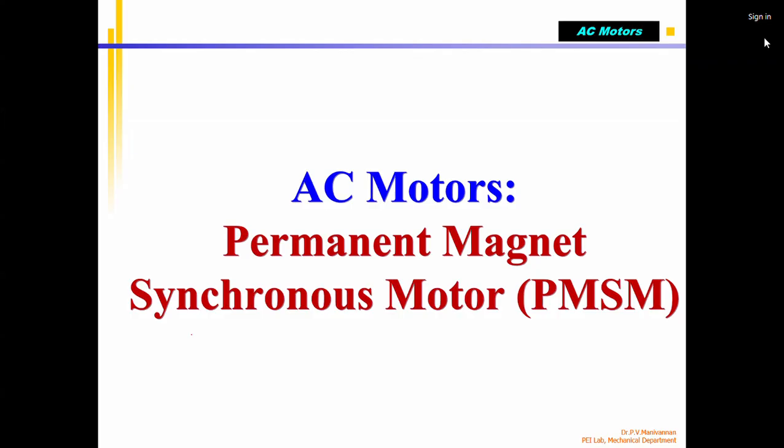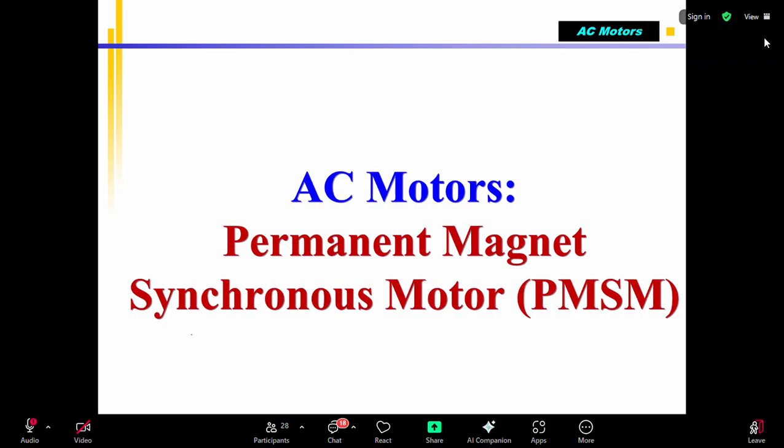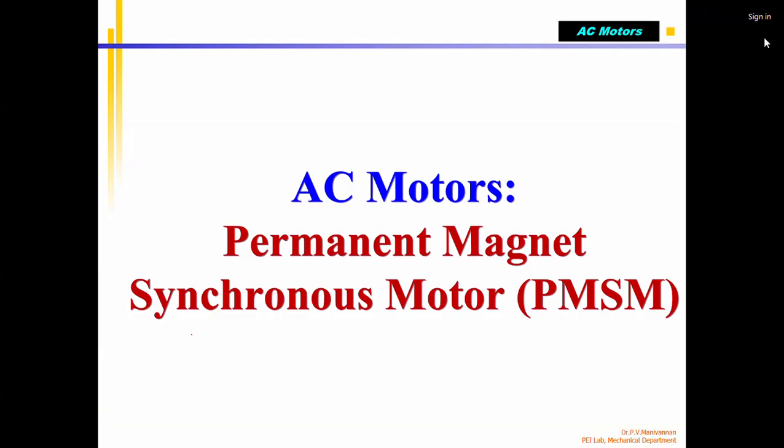That you should not operate. Generally, when you operate your machine, you should operate it lesser than this resonance frequency, up to 80% or 85% only. So if the resonance frequency of the motor or the engine or rotating part is, say for example, 5000 RPM, you cannot go beyond 4000 RPM. If you operate at resonance, the mechanical structure will break. Resonance can break your machine itself. That depends upon the mass and the stiffness of the moving parts.